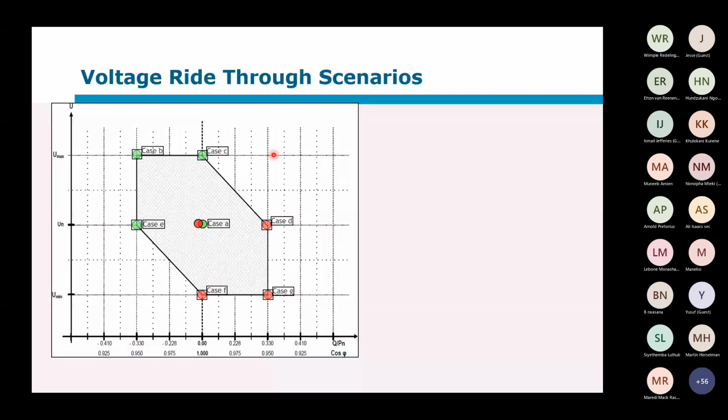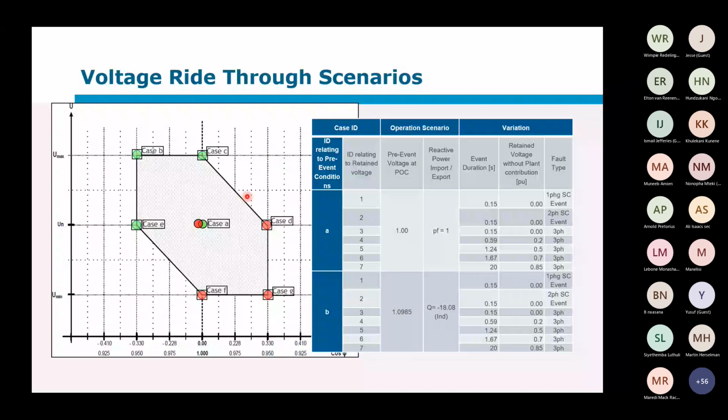But they must be able to provide the reactive power down to 20% of the active power output. So they must be able to actually operate at a worse power factor than the 0.975. And here at low power outputs, there's strict requirements. We have looked at this graph just now.